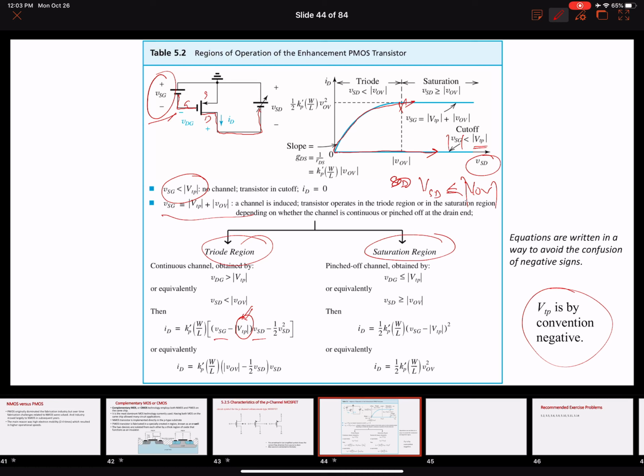And again, why did we reverse the polarities? Because rather than giving a positive voltage to the gate electrode, now we give a negative voltage to the gate electrode to push down all the holes to create a depletion region and subsequently attract the holes from the source and the drain to the channel to induce a P channel for a PMOS. And similarly, the battery is opposite.